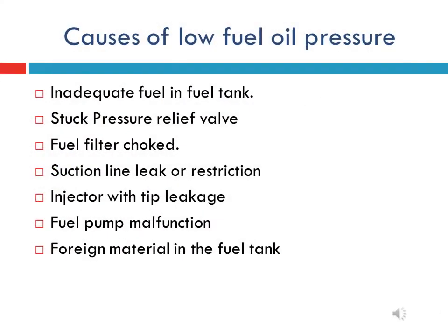The causes of low fuel oil pressure in the system are mentioned here in this slide, which can be easily understood. First is inadequate fuel quantity in the fuel tank. Second is a stuck pressure relief valve. This is basically related to sight glass number 1 or return fuel sight glass.